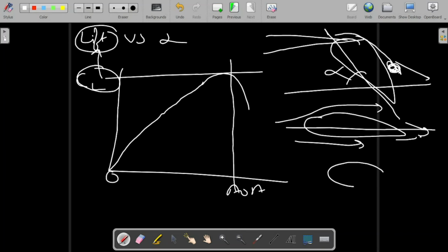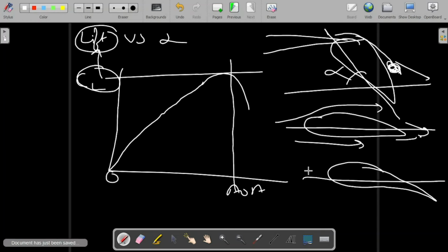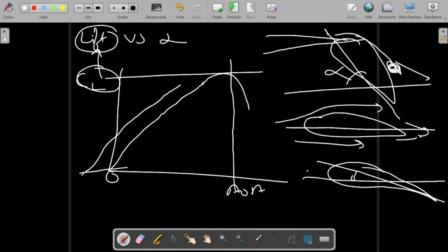But if you speak about the cambered or asymmetric aerofoil, even at 0 degree angle of attack, it creates a lift. So for an asymmetric aerofoil, the curve goes like this, and as you can see, at 0 angle of attack there is also some coefficient of lift. So this is the first relation between any aerofoil, angle of attack and the lift generation.